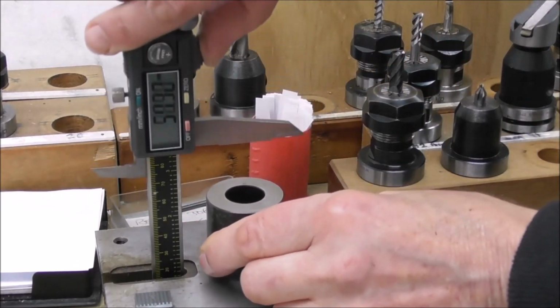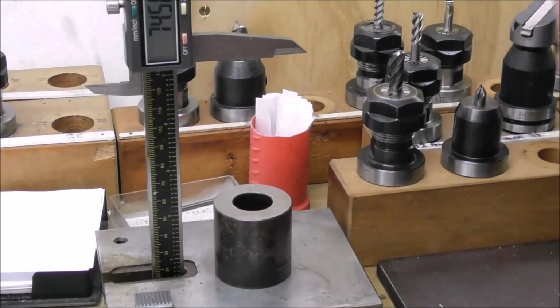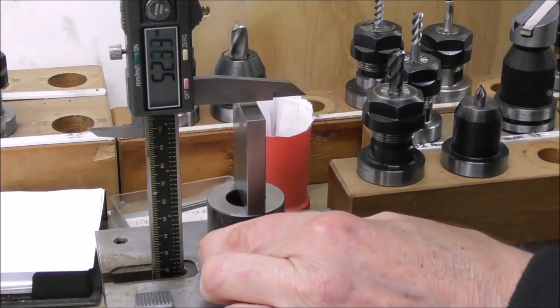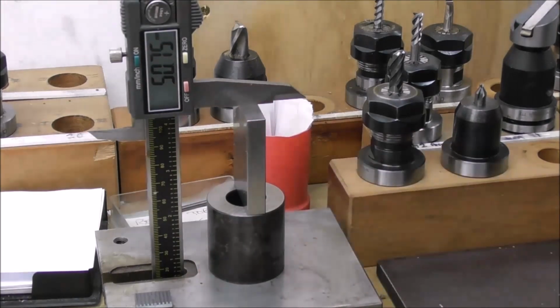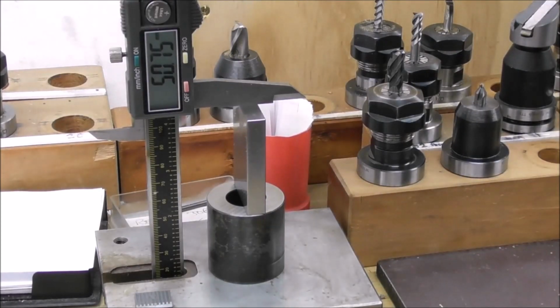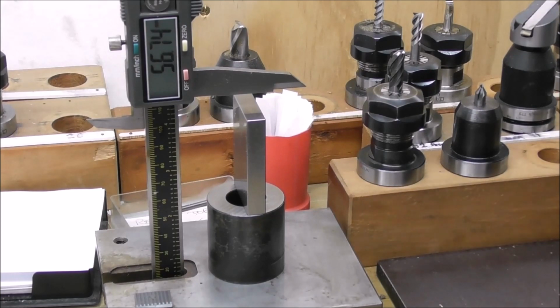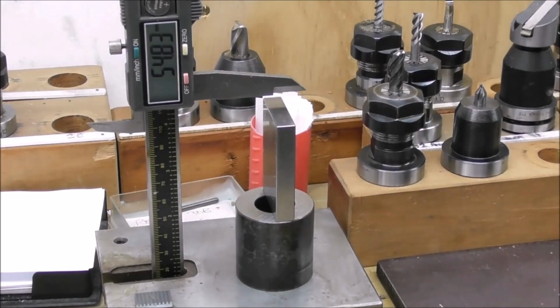Of course, every system has errors. If I zero this one, for example, there it's zeroed, and I put in a slip gauge. This is a 2-inch slip gauge, so that's 50.8 millimeters exactly. You can see there I'm getting 50.75. So there's 2 thou error there. It's measuring it shorter. Whatever system you use, there will be errors in your measurement, and there's the error in the compression when it's mounted in the spindle nose. So measuring your tool lengths off the machine is not a highly accurate system.